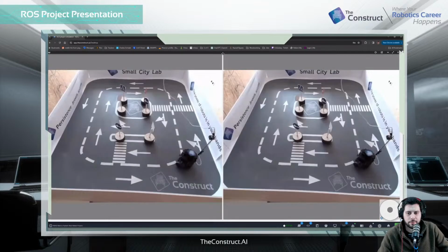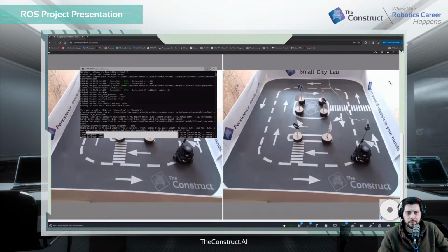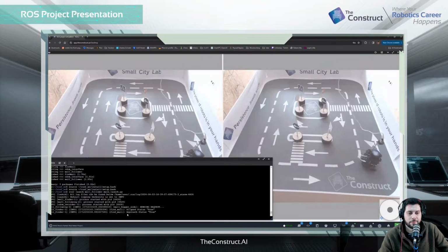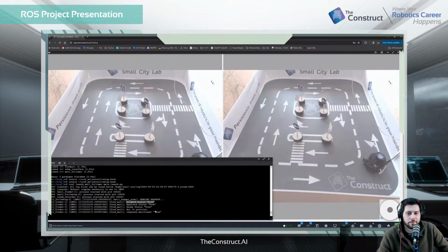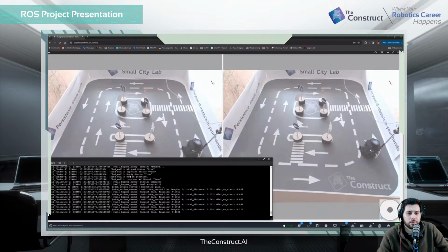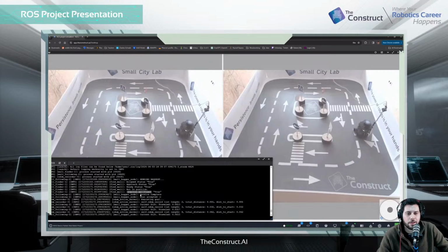Okay. So starting out, it should be looking for the nearest wall. It's going to be giving me indications of where it's at in its wall finding status. So we see aligned true, which means it's lined up to the wall. Then we get approach true, so it's approached the wall and got to the right distance. Then we turn, get the wall on the right side, and we see a ready status. Then it tells me that it's in position. The wall is found. Then we say the service is complete and move on to submit a goal for the odometry and start the wall following.